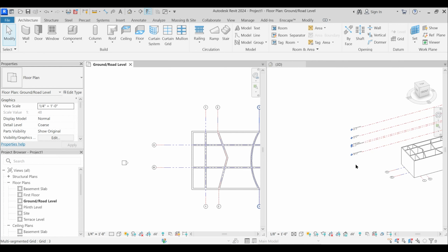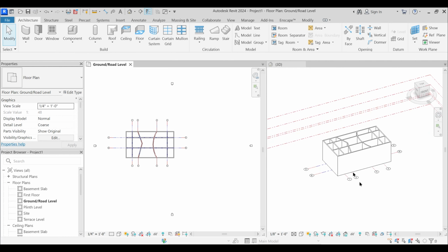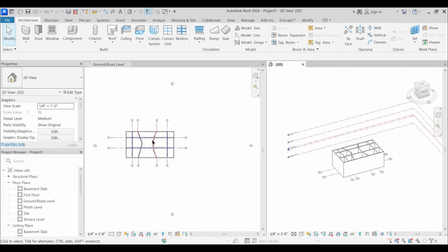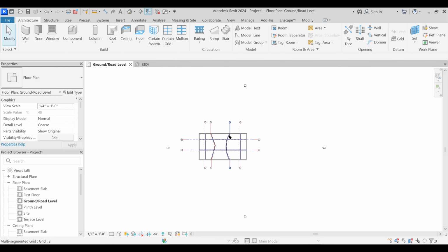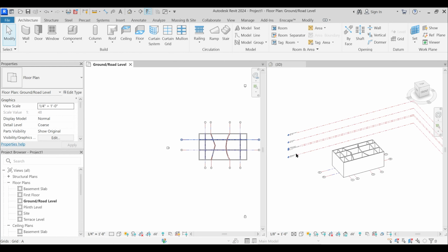And just like AutoCAD, where we have Z enter, E X enter for zoom extents, in Revit the shortcut for zoom extents is ZA. And that will toggle both of these views. Again, if you want the expanded view of any of the views you want to expand, select it and press the opposite of WT, that is TW. So that will again bring the expanded view. And WT is the tile.